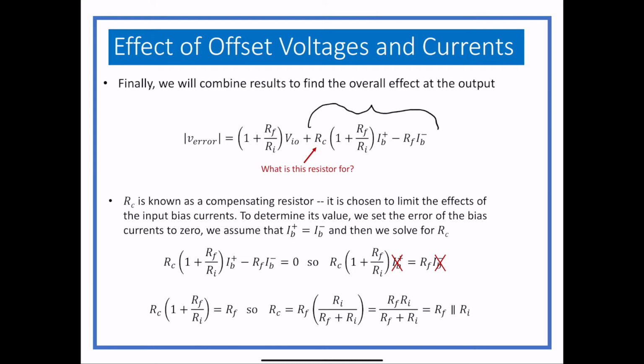And there's already a problem with that, because anytime you take the parallel equivalent of two resistors, you're going to get a value that you can't find, unless you have some really, really special resistors. If you can possibly find two 10Ks and take them in parallel and then go find a 5K, but that's generally not the way circuits work. So already there's going to be a little bit of trouble finding a compensating resistor that has that exact value.